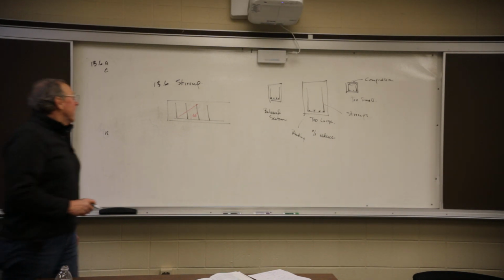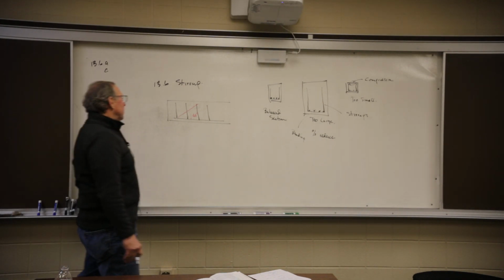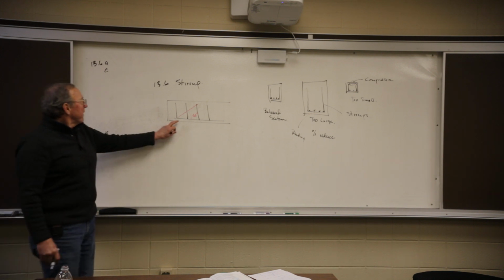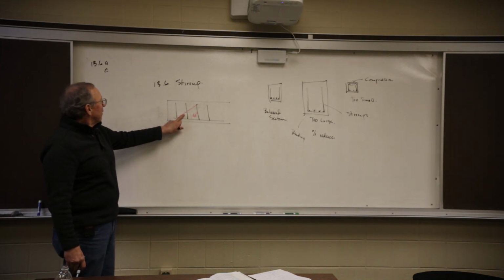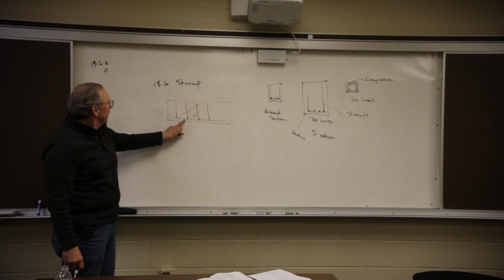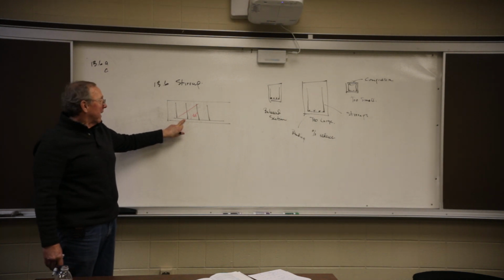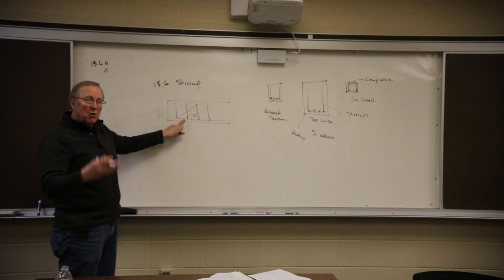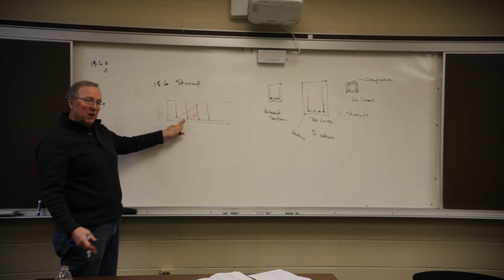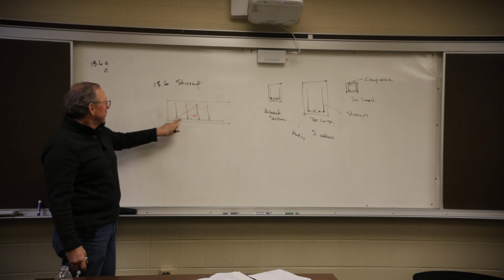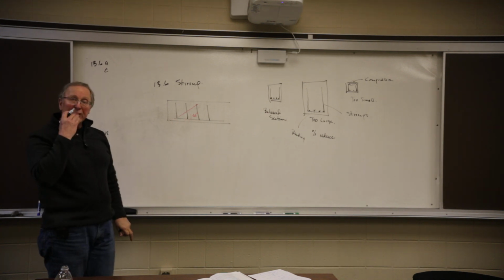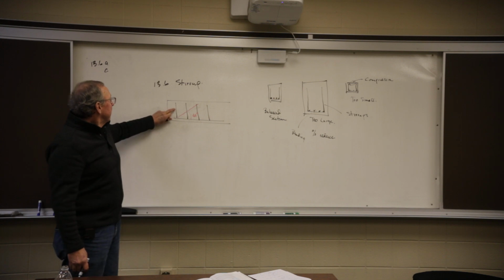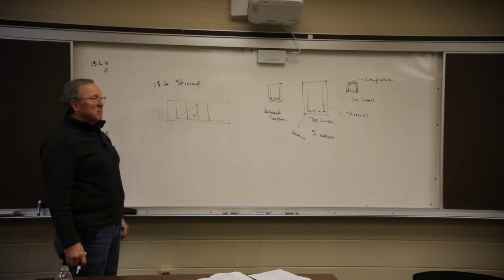Okay, the 45-degree angle, we indicated that part of that component, the horizontal component of the shear force, is taken out by the longitudinal steel. We're able to do that because when the shear is biggest, the moment is the smallest. So we don't really need the longitudinal bars out near the end where we need it for shear. And then the vertical component is taken out by the stirrups.